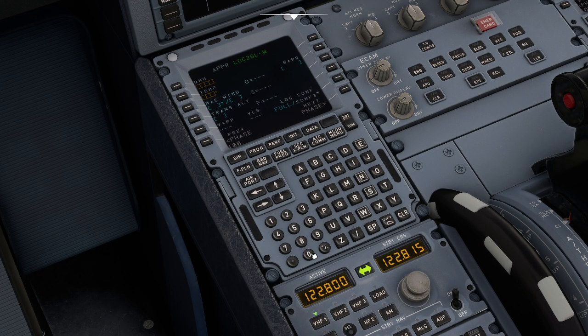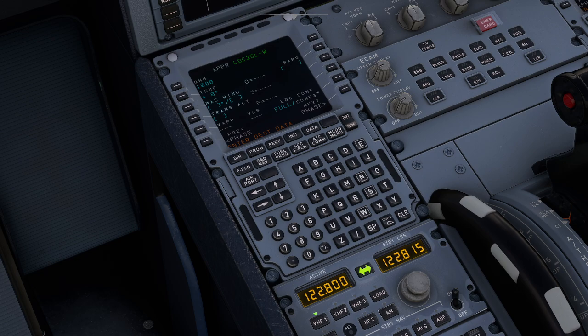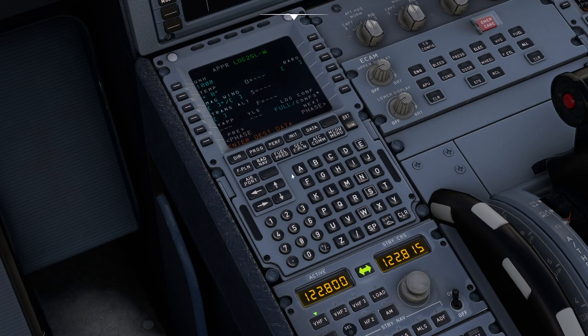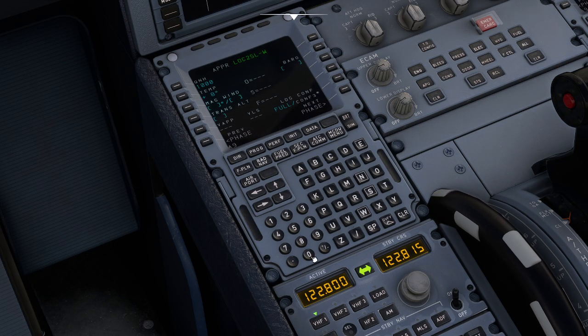I think we need to add another 0 and then I put the QNH. QNH is right. And the temperature given is 8 degrees. And we put it over here. And then wind is 190 at 6. So we configure that 190.